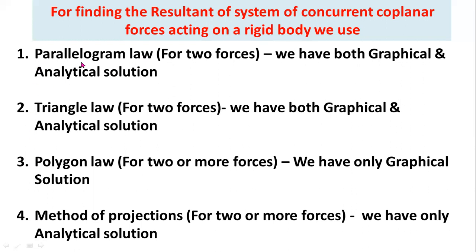First method is parallelogram law of forces. Parallelogram law of forces is useful to determine the resultant of two forces. Okay, in parallelogram law of forces, we are using two forces.